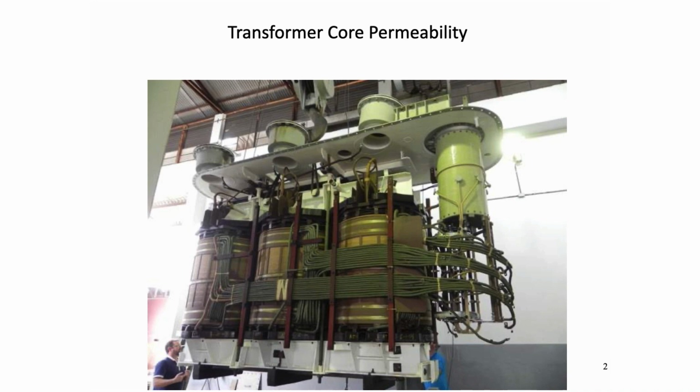This means that steel cores can carry a magnetic flux 1,500 times better than that of air. However, when magnetic flux flows in a transformer steel core, two types of losses occur in that steel. One is termed eddy current losses, and the other is termed hysteresis losses.